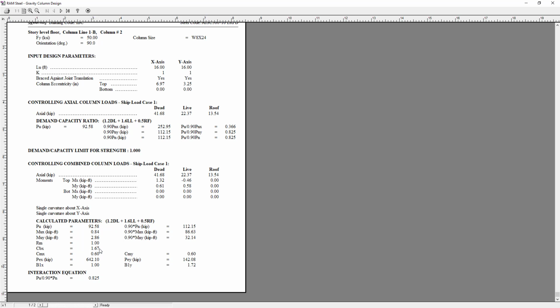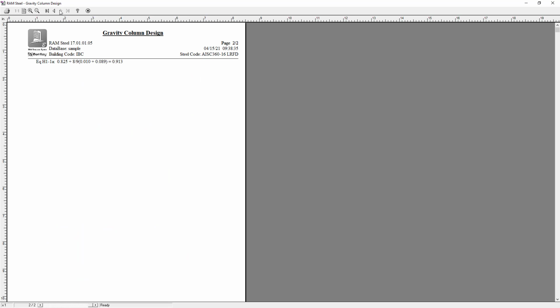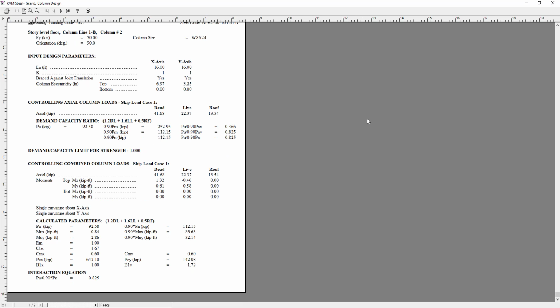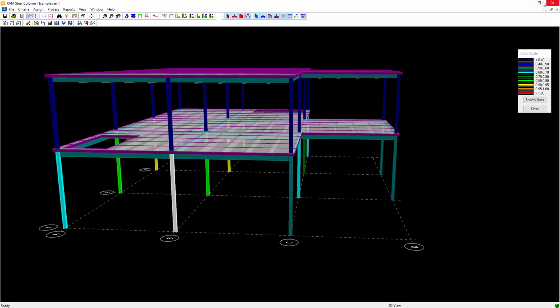You might be saying, didn't you check the box for 1? Yes, we checked it as 1 for beams. For columns, it's a little bit different here, apparently. So that's something to take a look at, but this is one way you can go ahead and verify where your beam design is, and here's our unity of 0.9. Okay, so a lot of really good information there, a lot of really good information that you can get out of this program, and a lot of amazing design that this system will do for you.